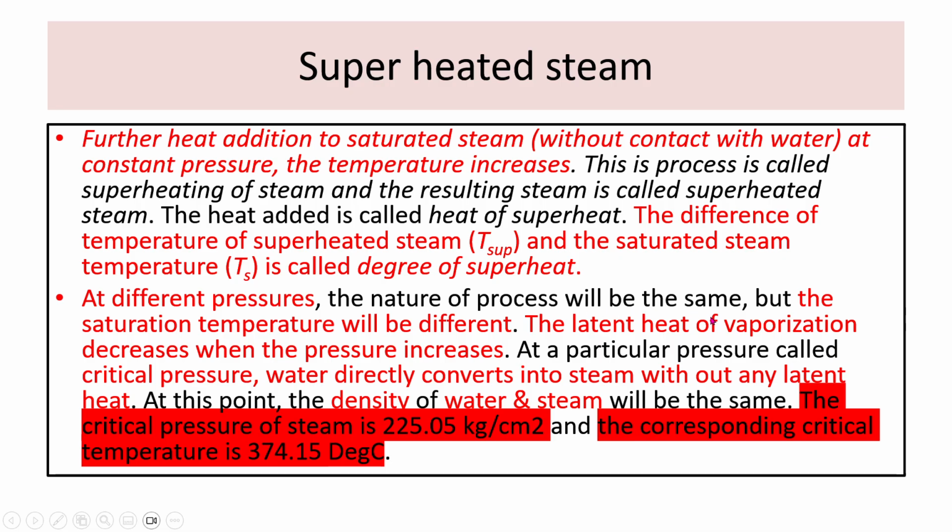At different pressures, the nature of the process will be the same, but the saturation temperature will be different. At different pressure, the saturation temperature will also be different. Latent heat of vaporization will decrease when the pressure increases.